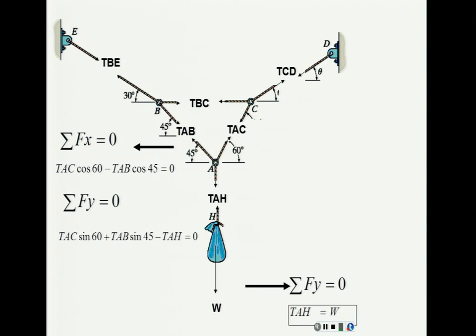But you have to be more practical and more logical with these types of situations and think, what type of structures are these? What type of elements are these? Those are cables. Have you seen in your life any cable that pushes? No, cables don't push. If they were rods, steel rods, it's different. Those are cables, so the only thing that a cable can do is pull. Hence, all the cables have to be pulling the particle, no matter what. You can have 0, but never are you going to have a negative value for a cable, because the cable doesn't push.